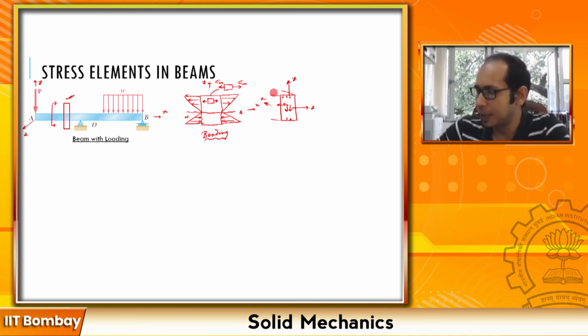So that essentially means that if again I am looking at this kind of configuration, because of these longitudinal stresses at the center of the beam, I am going to have shear stresses. Now see, the interesting thing is that in this shear stress, the arrow which I drew is about this section, the vertical line over here, and this arrow is about the longitudinal axis, about the x-axis.